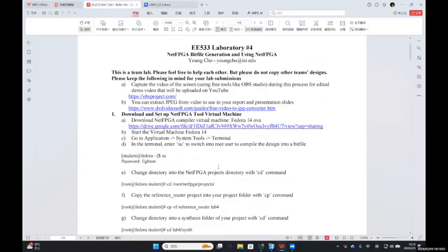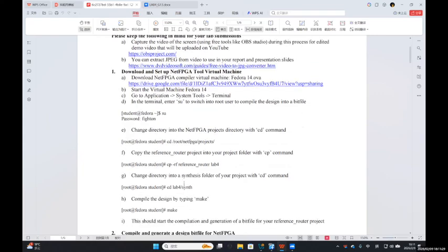My part is from part 1 to part 4, and these parts cover the complete preparation process before implementing and testing our own hardware design on the NetFPGA board. I will discuss how we set up a NetFPGA virtual machine environment to generate FPGA bit files, configure US VPN for remote access, and finally configure the NetFPGA working environment, including SSH and terminal management. Let's move to the first part.